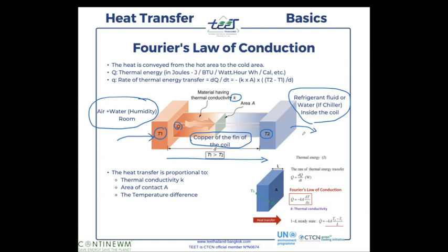What is interesting is not to know about all the details of the calculation, but something that is important for us to explain what's happening in continuum is we have to know that is the heat transfer. That means the speed with which we transfer is proportional to the thermal conductivity, the contact area. This is very important, the contact area, and the temperature difference. That's what you can see here in this calculation. That's what we call the Fourier's law.